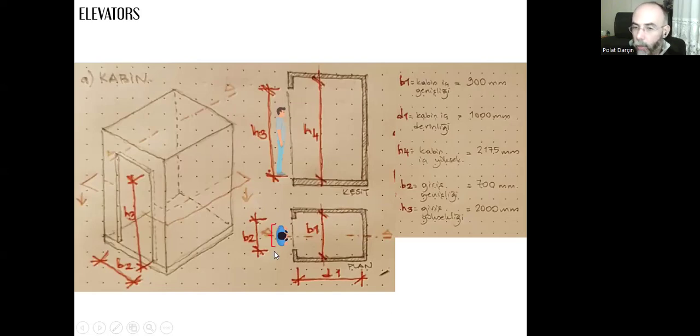So we have this width, and normally we take 60 centimeters for this width, but we don't want their hands or elbows to brush against the surface of the doorway or the walls. So we can add 5 more centimeters. So instead of 60 centimeters, including 5 and 5 on either side, we can have 70 centimeters. That's why it's the minimum. 70 centimeters is the minimum. It's only for a person to pass through without hurting their shoulders or elbows or hands.